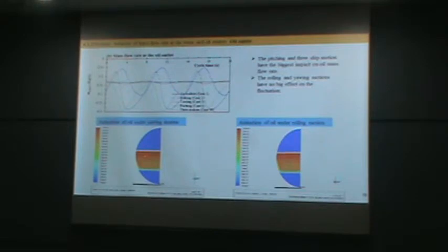Now I will compare oil separation efficiency for no-motion and ship-motion cases. From this table, we can see the rolling and yawing have no significant effect on separation efficiency, and for the case of pitching and three-angular motion, the oil separation efficiency decreases significantly from 98% to 63%.